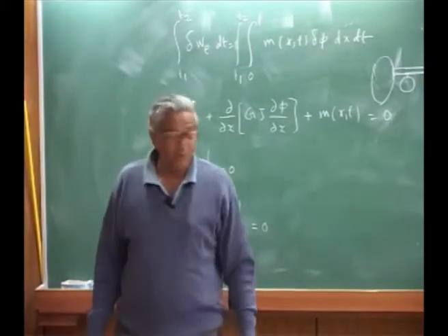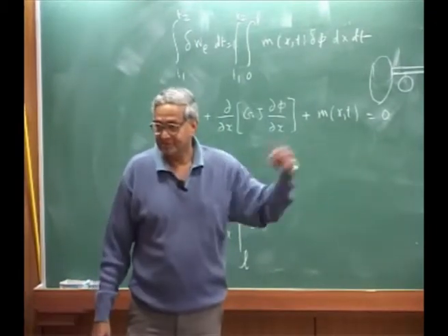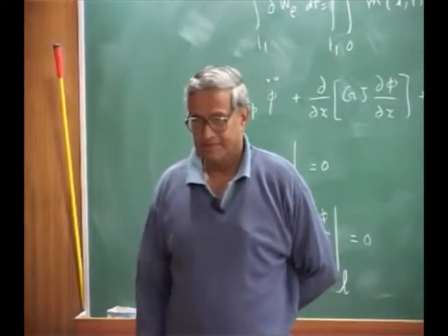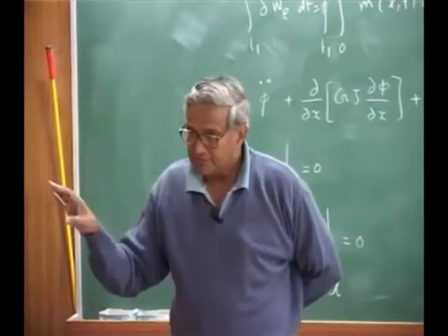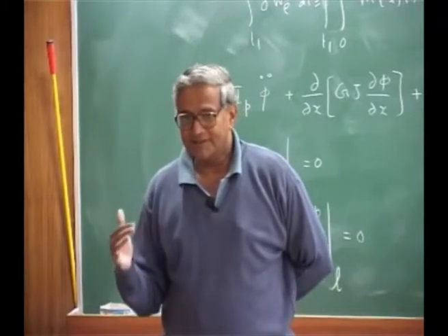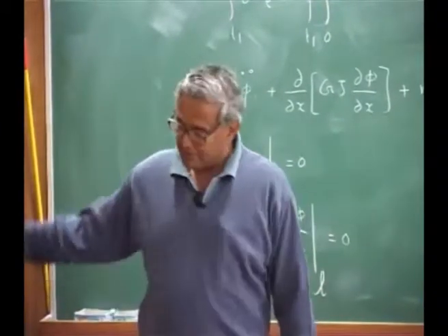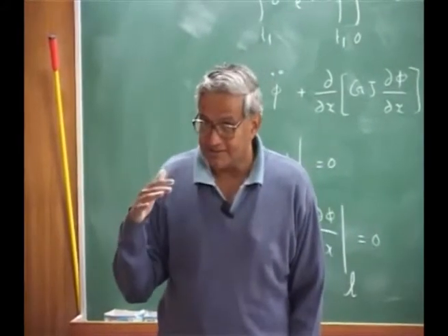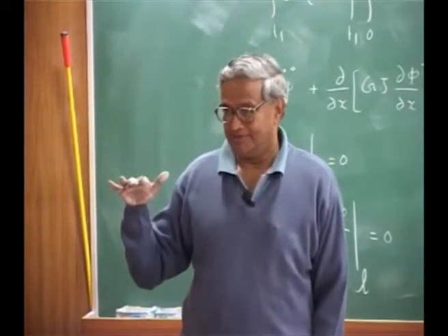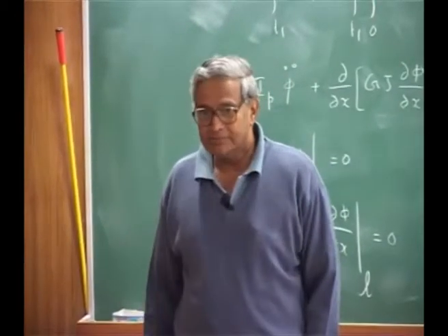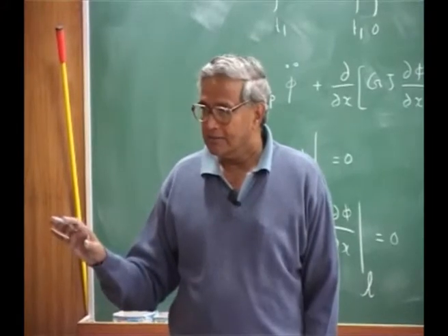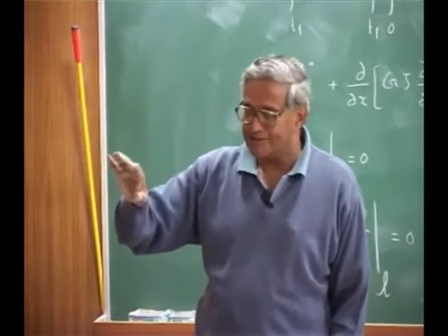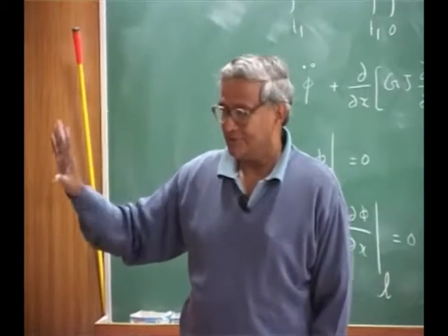Okay. Whereas when you go to vibration problems, these are partial differential equations. So what we do first is the free vibration problem. What are the free vibration characteristics of a beam in bending and torsion? That is the first step. Then, using that particular solution, you convert them into ordinary differential equations. Actually, you do separation of variables in the free vibration, and after that convert it into ODEs, ordinary differential equations.